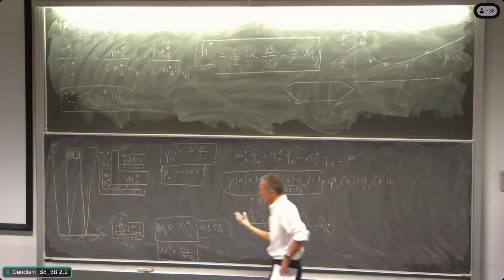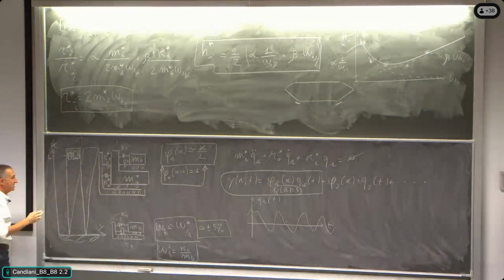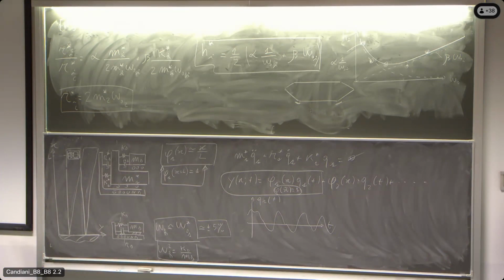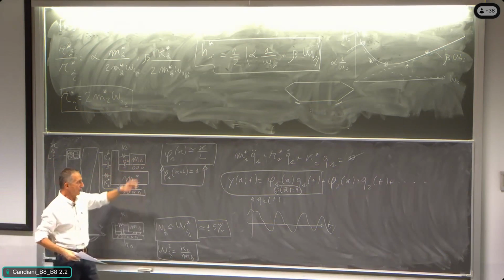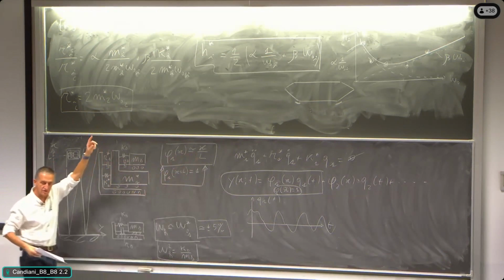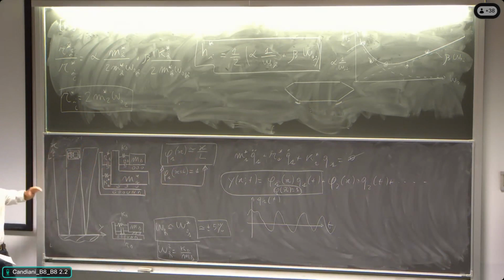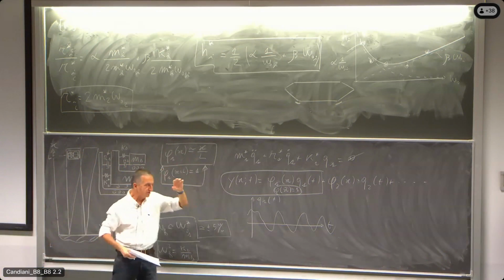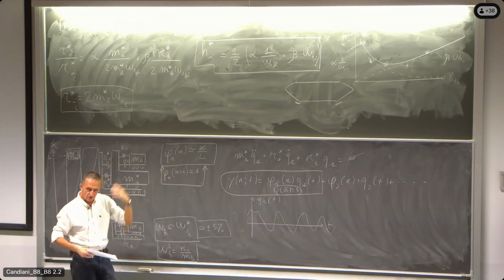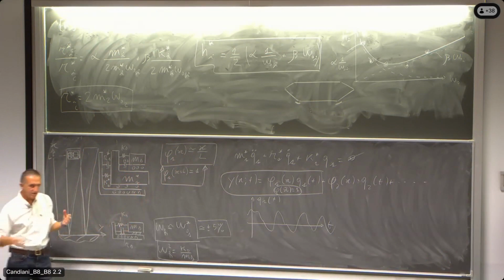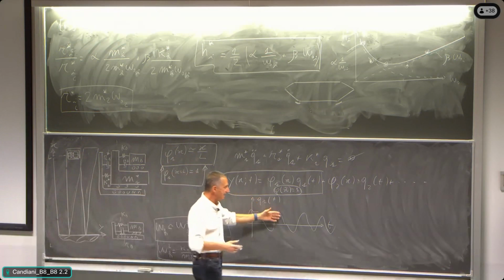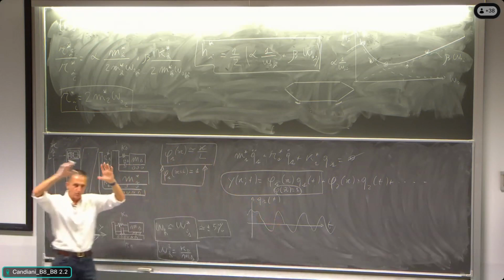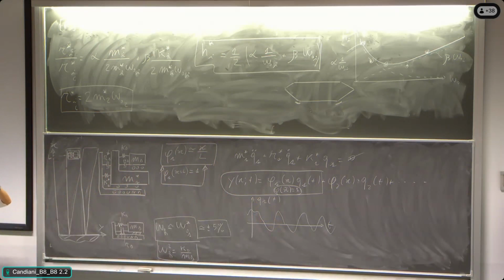So here we are touching with our hands that the normalization of the mode shape is extremely relevant, because if I am normalizing the mode shape in this way, so that when I am at the top of the building, with x equal to L, the mode shape is equal to 1, and I make all my calculations with this hypothesis, as a consequence the function Q1 of time is not something that is far away, just in the world of ideas.